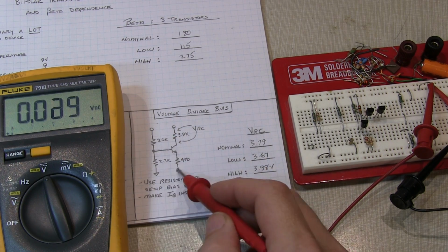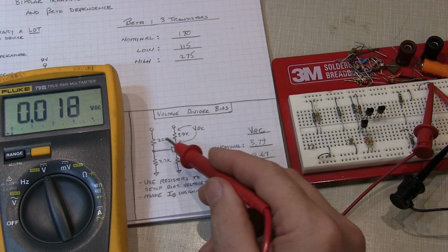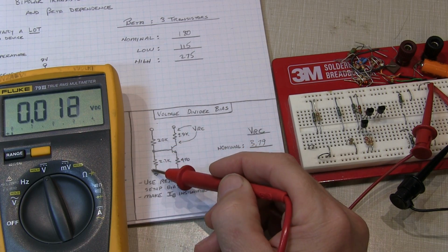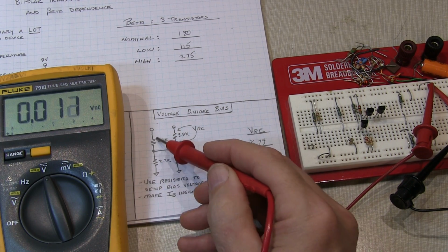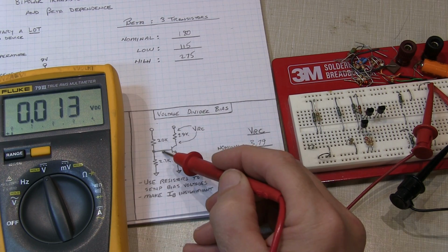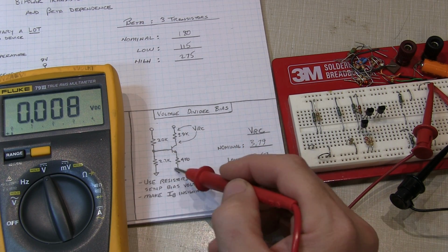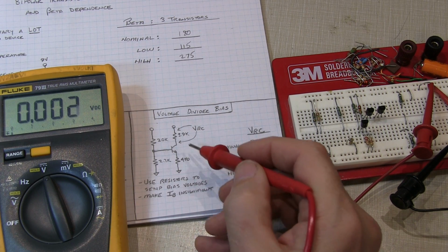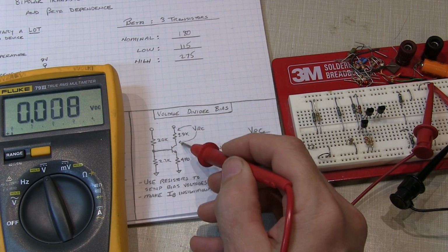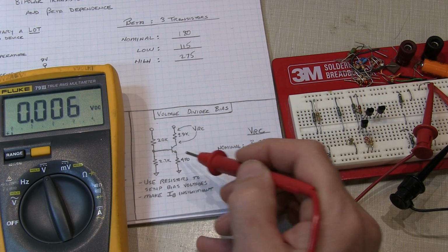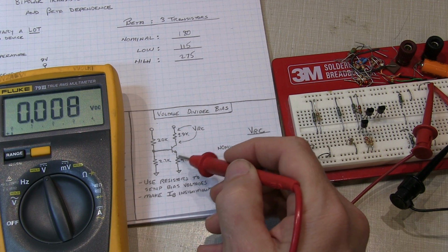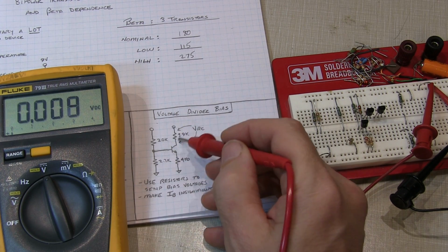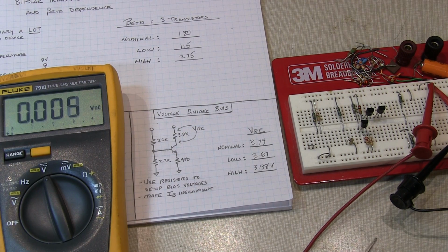This is a very, very common bias arrangement that you'll see. And those are the design rules, if you will, for this: make the current in the bias path relatively large compared to the base current, and then establish a reasonable voltage across the emitter. In my case, I picked about 0.5 volt. That wouldn't really impact the amount of swing I've got available too much by only taking 0.5 volt away, but it also gives me the ability to set up the bias current in a nice fixed way. So we've got a nice fixed bias across the collector resistor.